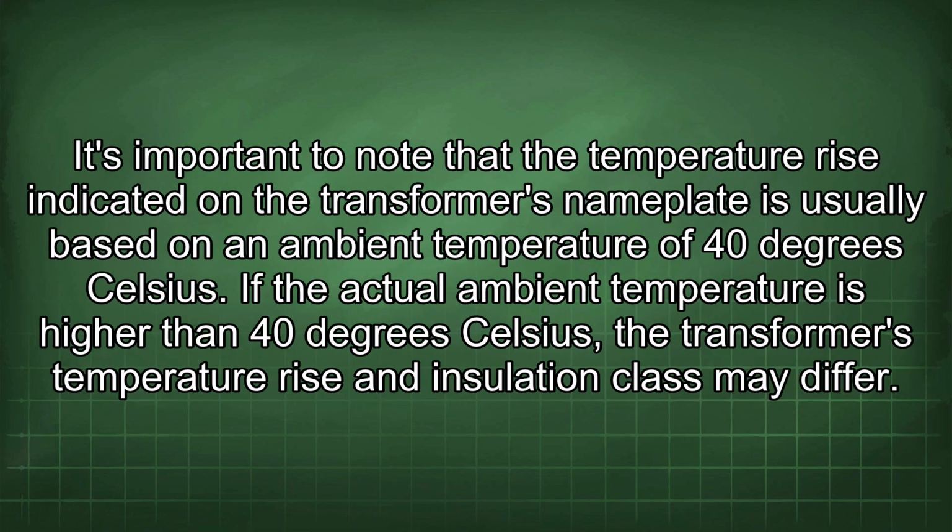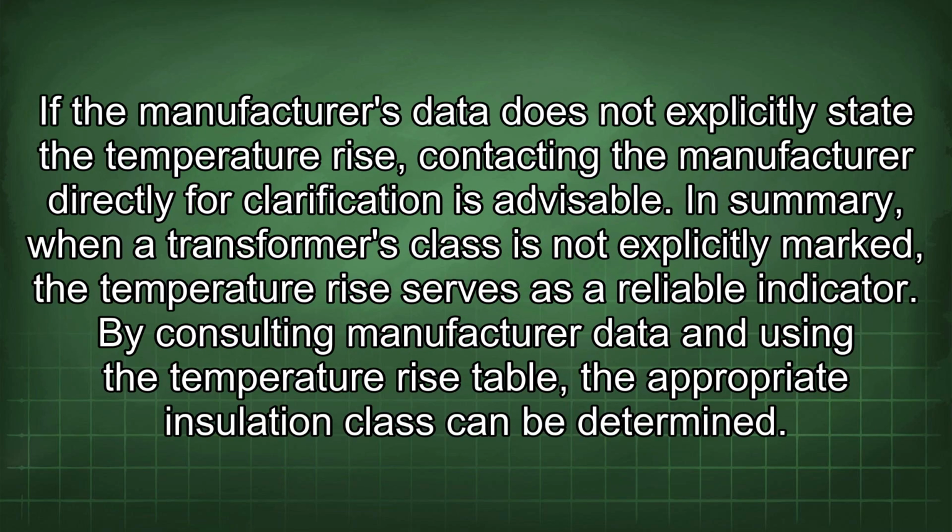It's important to note that the temperature rise indicated on the transformer's nameplate is usually based on an ambient temperature of 40 degrees Celsius. If the actual ambient temperature is higher than 40 degrees Celsius, the transformer's temperature rise and insulation class may differ. If the manufacturer's data does not explicitly state the temperature rise, contacting the manufacturer directly for clarification is advisable.